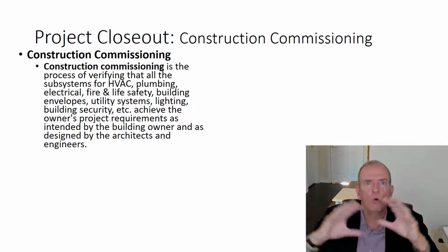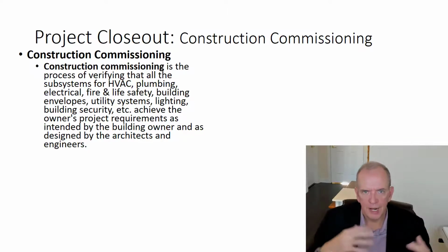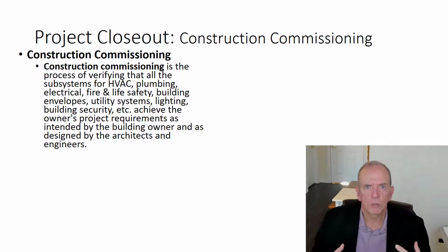Commissioning is a whole huge subject unto itself. It's gotten contractors really nervous over the last 25 years, and it's ramping up as we speak, because the level of complexity in building systems has escalated tenfold over the last 25 years. When you have different systems that have to talk to each other, it becomes more complex to ensure that they actually talk to each other properly. You have to make sure, for occupancy, that the elevators return to the first floor when the alarms go off, and that they don't go to the floor where the fire is, as has occurred. So these systems have to be tested and made sure they're functioning properly. That's the whole commissioning program and inspection process that takes place.